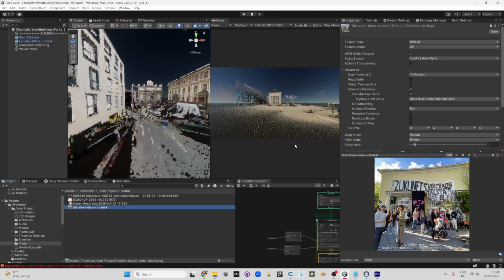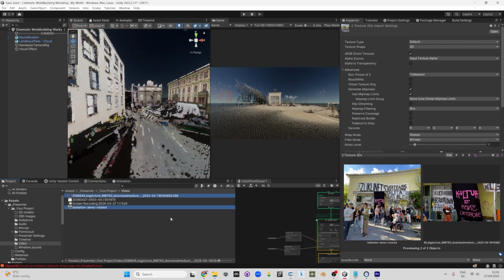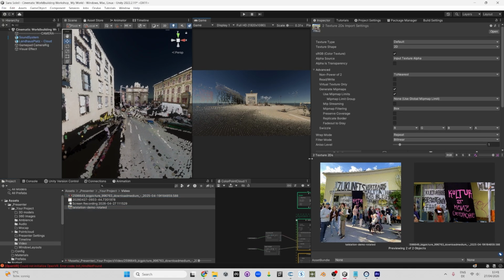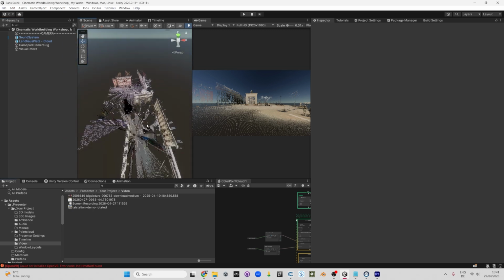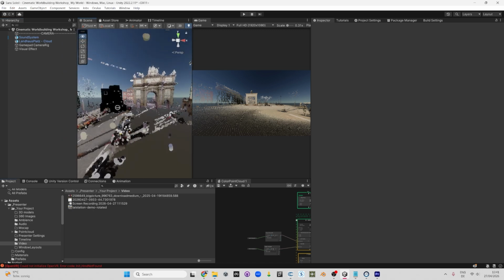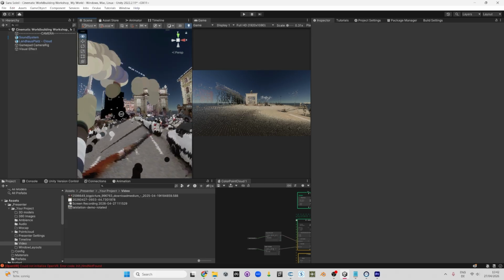We will treat the images as textures, like in any other 3D software, which go into the albedo channel, or the base map, so to say, in Blender. For that we first need to create a three-dimensional object so that we can assign these images as textures.